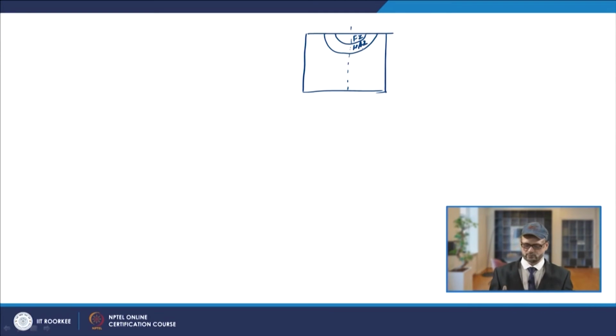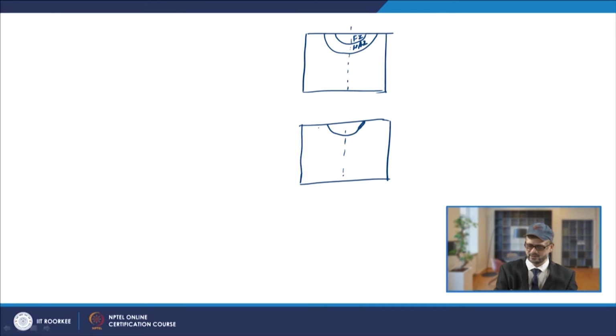Now, if you are preheating to maybe 250 degrees centigrade, it was seen that this zone got widened. The fusion zone, as it was earlier here, became somewhat wider. Similarly, the HAZ also became somewhat wider. So, the HAZ was seen to be wider when we did the preheating. Then, the preheating we do depends upon other factors also, geometrical or technological factors, which determine the extent of preheating in those cases.